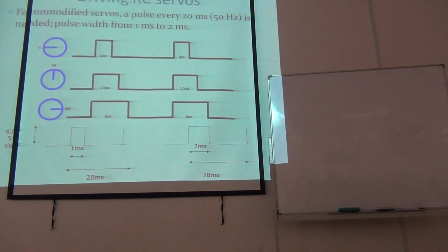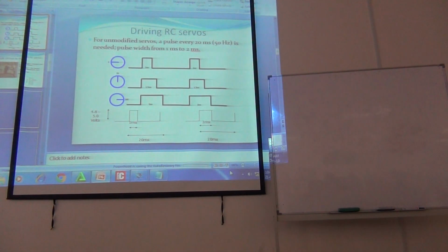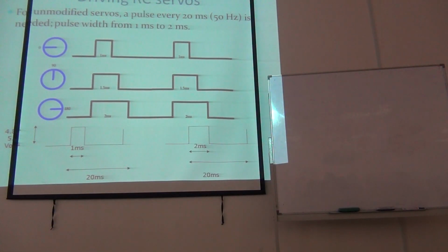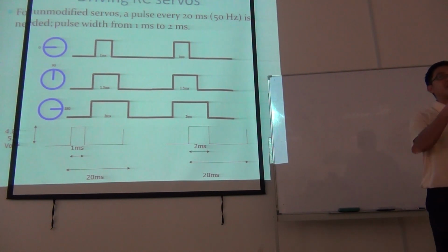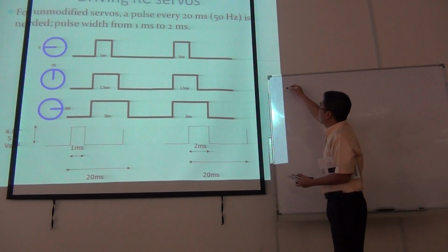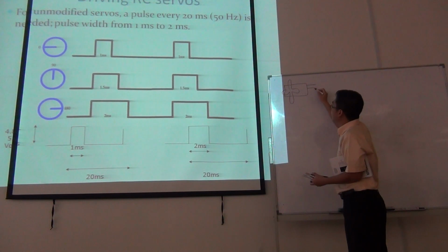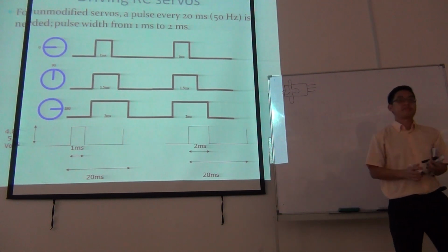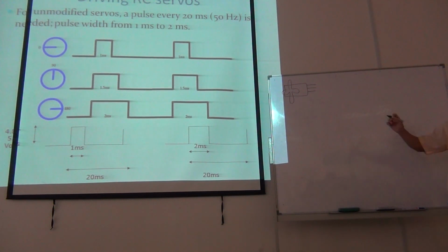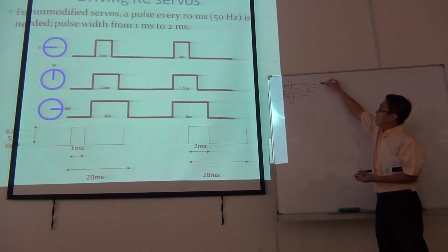The only difference from the DC motor is that your servo motor has only 3 connections. If you can see on the board, for example, here is your servo motor, there will be only 3 connections available. One is the positive, which is the 5 volt.